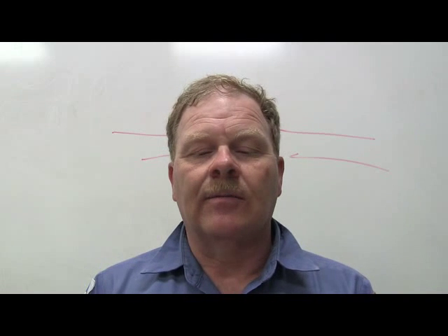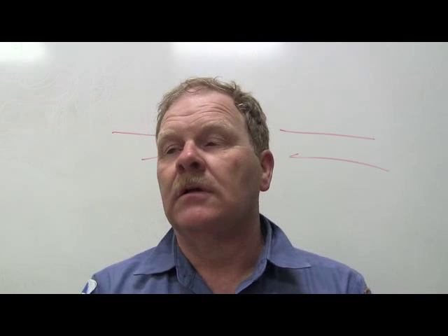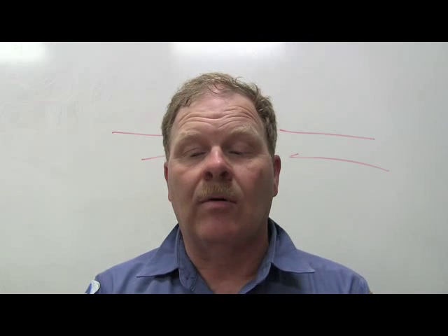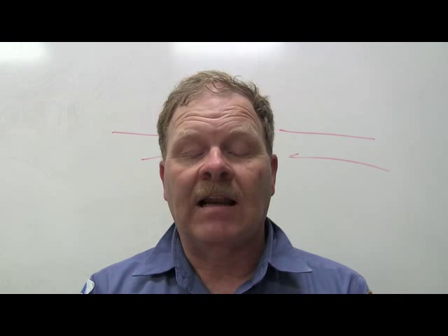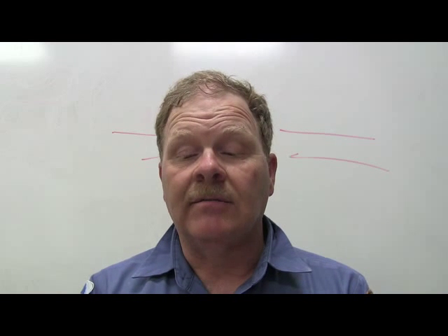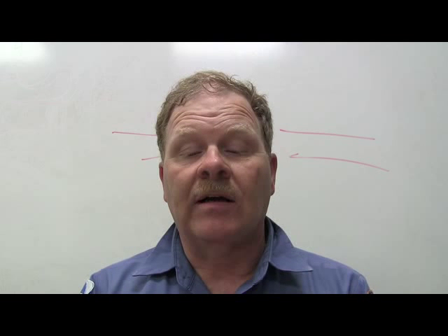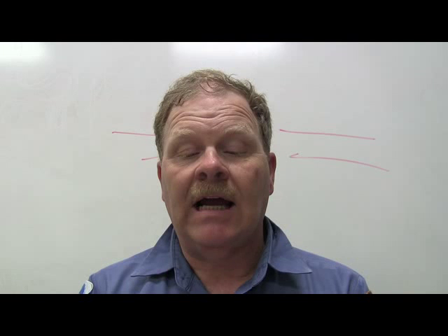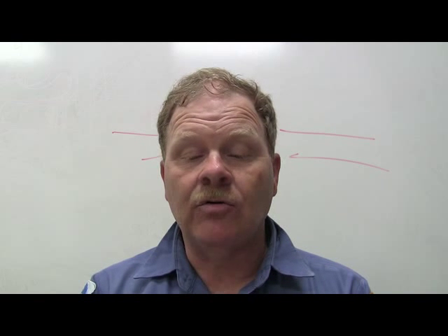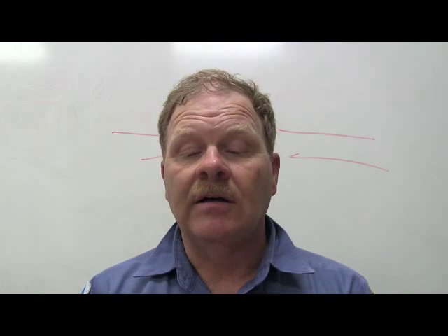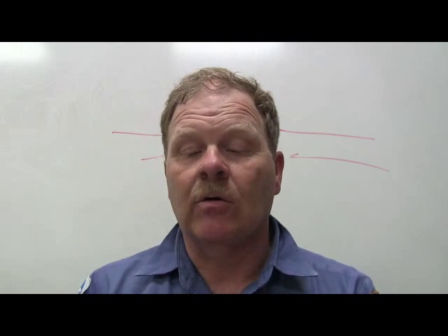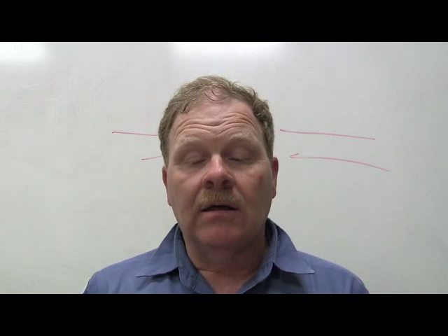A variable displacement compressor uses what? Number 21, that's B actually, a variable angle wobble plate. I like to call that a swash plate, but they call it a wobble plate. Which of the following is not a major component of most compressors? A, clutch. B, fins and tubes. C, piston and rings. D, reed valves. This is going to be a B. We don't know fins and tubes on there.